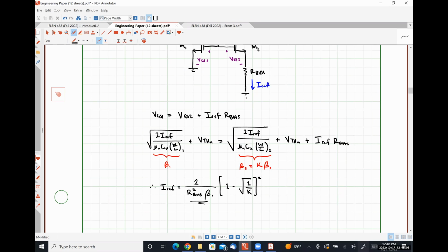So it's really just this part right here multiplied by a factor of 1/4. And it's a very trivial relationship to figure out what R bias needs to be to get a particular current value. Also happens that we'll have a constant transconductance, which is why this is also called constant transconductance biasing.